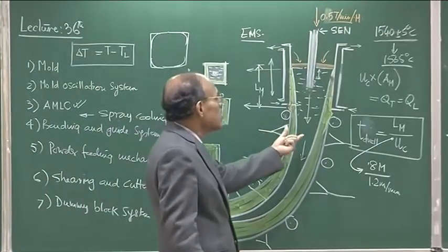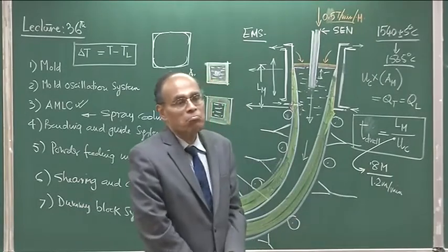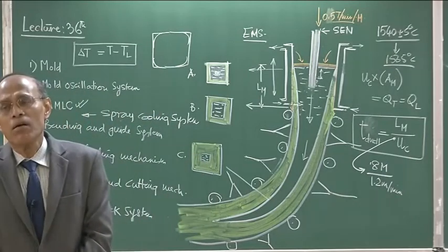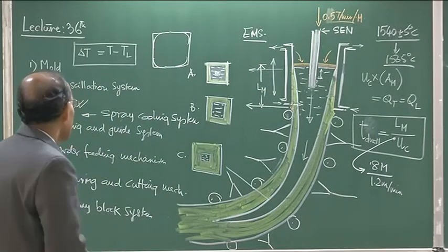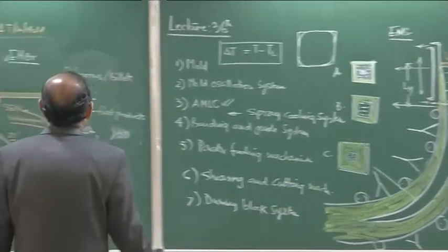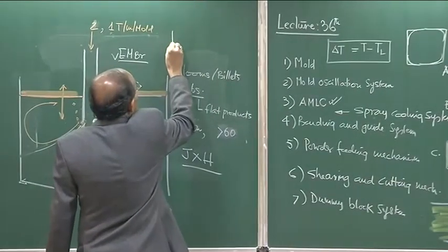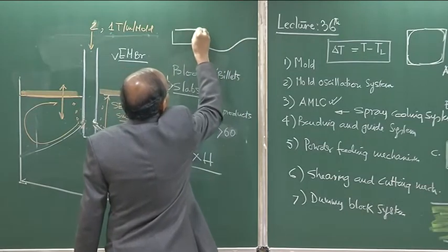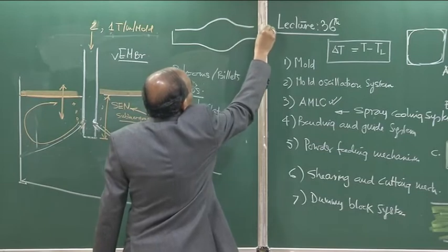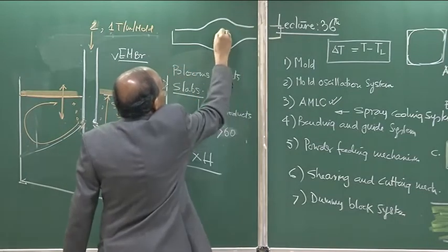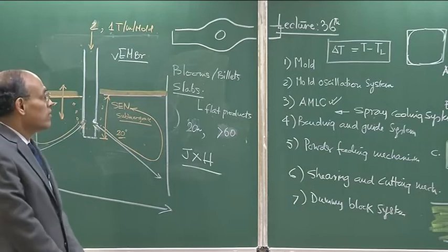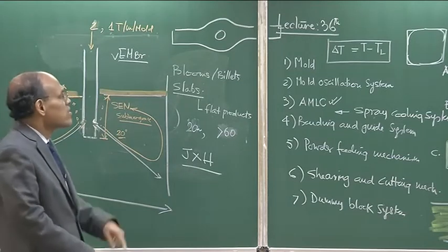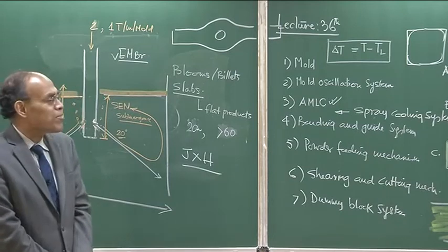So, these are very popular techniques for controlling the finer properties of steel which are being produced by continuous casting machines. Beyond this, we have thin slab casting as I have indicated, as well as twin roll casters. In thin slab casting, the mold design is a funnel shaped design. This is a thin slab mold design, and the submerged entry nozzle design is also completely different. So these are evolving areas, and sometimes they work, sometimes they produce defects.